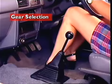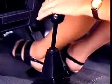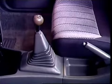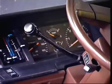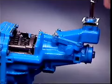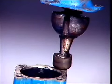This section examines gear selection. A gear shift lever allows the driver to manually select gears via a gear shift mechanism. The lever can be mounted remote from the gearbox, on the floor, or on the steering column, and connected to the gearbox by a rod linkage or cables. It can also be mounted in the top of the gearbox, where it acts through a ball pivot in the top of the extension housing.